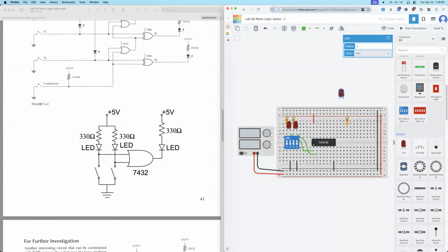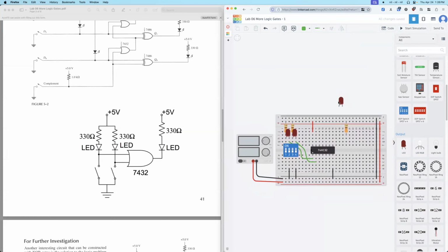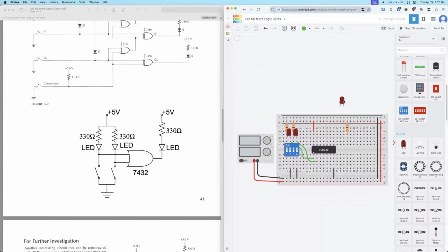Okay. So flip. Oops. Okay. Then this one, so the negative can go down a little bit. So the negative terminal of the LED connects to pin 3 output. So let's go here. So pin 3, this is output.